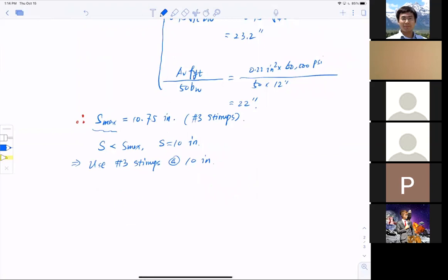So that is number 2B. Sorry for being late reading the message. 0.75 phi in these cases, yes. So phi, pay attention, for shears always 0.75. Strength reduction factor for flexure changes, but for shear is constant.